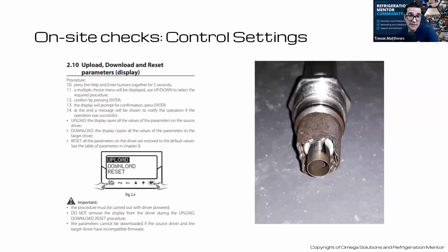Yeah, that there can cause a massive amount of issues. Now, your high pressure valve is really the control of your system. It's controlling your gas cooler condenser, it's controlling your receiver. And then you start plugging that up, it could cause issues in a lot of different places. You could be out at a case, that last case is not feeding. You could be looking at the flash tank. Hopefully you understand that the high pressure valve goes into the flash tank receiver, but it could cause some issues in other places in the system, but it comes back to the flash gas.